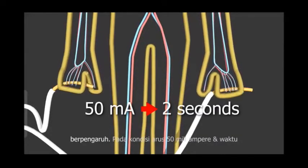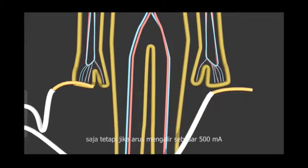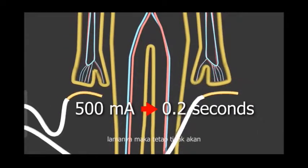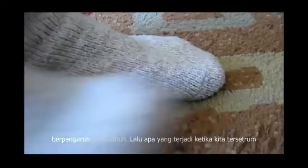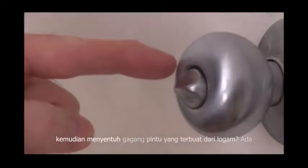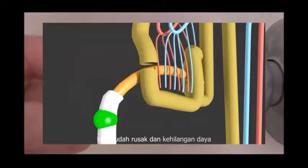At 50 milliamps, if you manage to let go within 2 seconds, then you'll be okay. But if the current is 500 milliamps, then you have just 0.2 seconds, 2/10 of a second, to let go and still be okay. What about when you get a shock by rubbing your feet on carpet and then touching a metal door handle? There could easily be a few thousand volts there, enough to break down your skin's resistance.